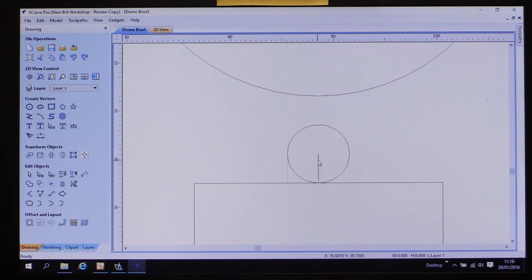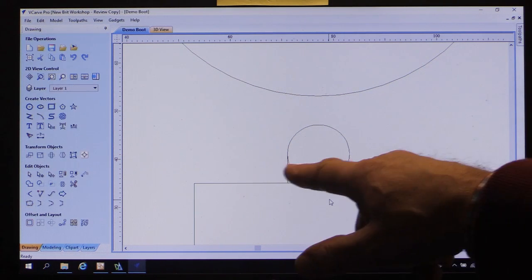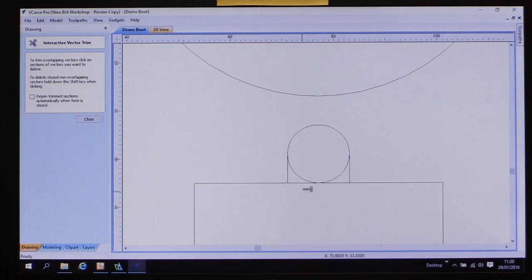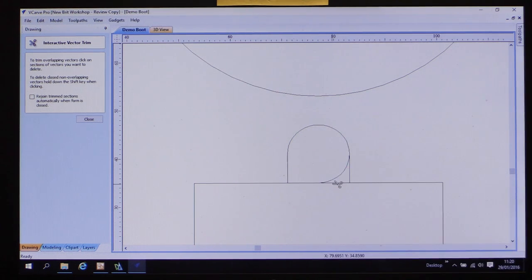At this point, I can just delete that line I used to create the circle. Now let's do the line command again and do it from here. There we go. But I don't want this bottom piece of the circle. So I'll just go across here to the pair of scissors, and I'm going to cut this part of the circle and this part, because it cuts until it meets a line. So it's only cut that quarter away, and I'll get the other segment there, and that's fine.